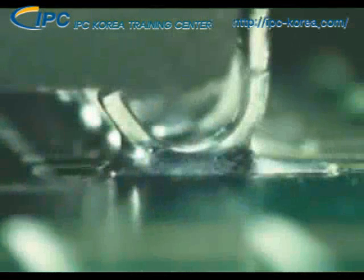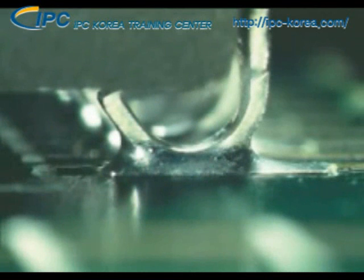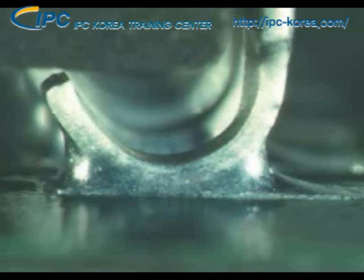The solder covers all of the land and the lead. The texture is smooth and shiny. The outline of the lead is visible beneath the solder. The amount of solder here is just about perfect.